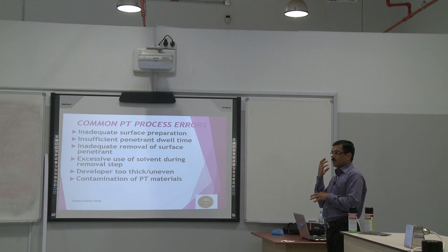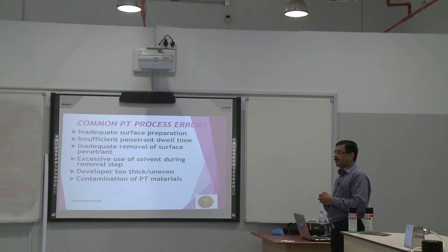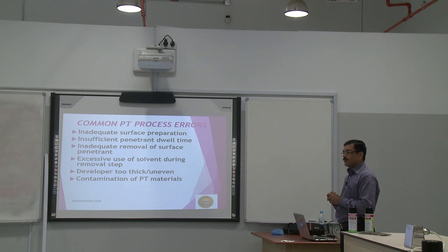Yes, it bleeds out. If you stay more time, can this penetrant evaporate? Yes. So if the defect is deeper, of course, maybe 2 times, 3 times you wipe out and apply developer, maybe the indication will still come. It will bleed out.